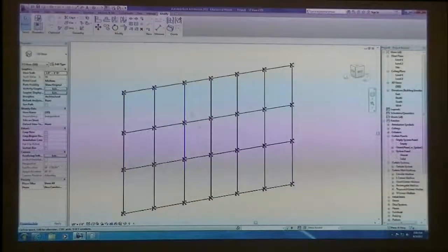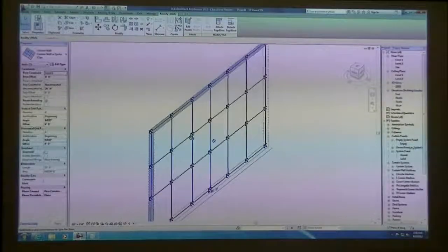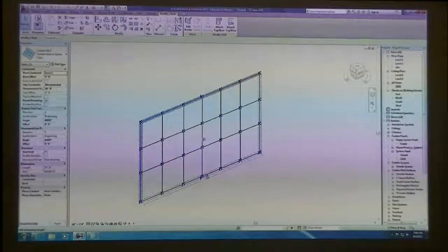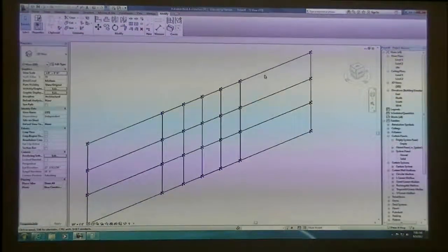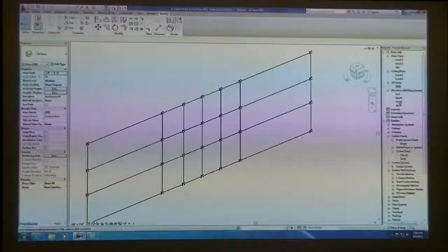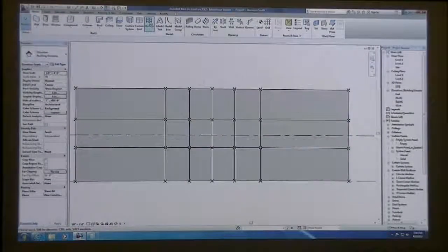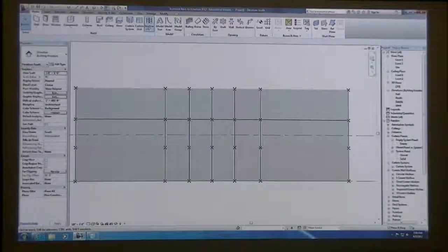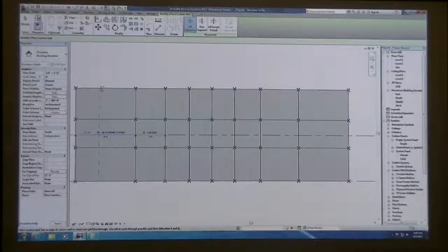And then you've applied that grid system all over your whole entire wall. So if you were able to change your dimension of your wall, let's say I make it 60 feet long, look at it in one of my elevations, and if I add more grid lines, you will start to get more spider clips to appear. So I can start adding grid lines, and for each division I make, I end up with spider clips on all the different corners.